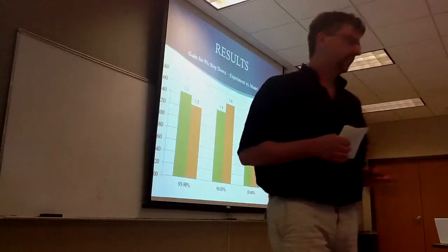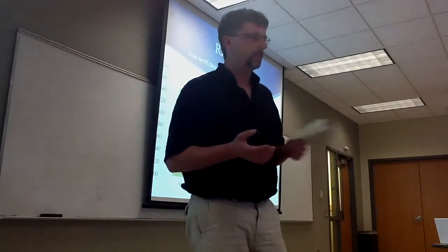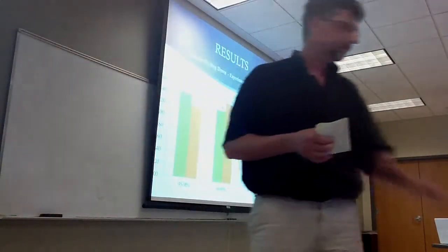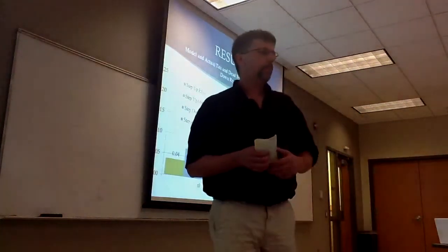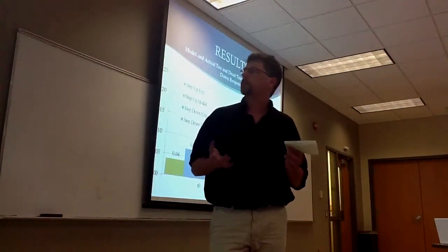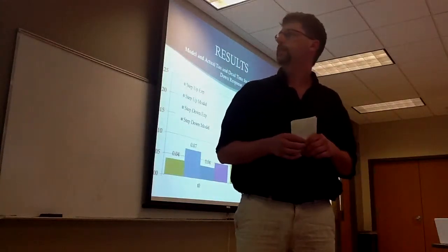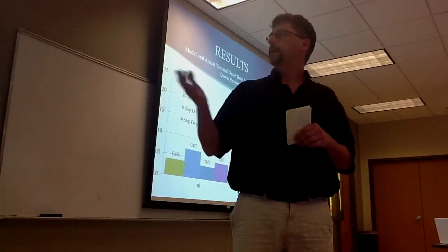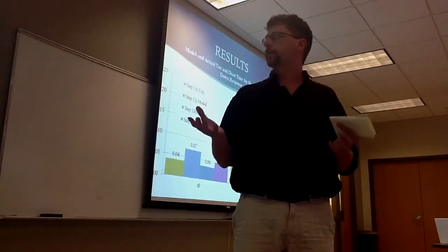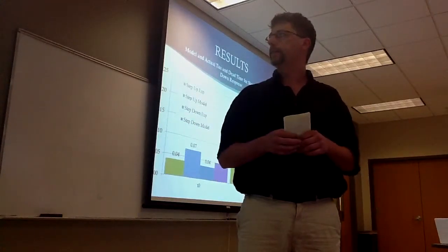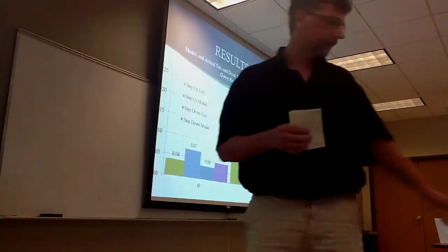Similarly, we did the same thing for the step down. There's 1.5 versus 1.3 for the step down for the actual versus the model, for example. The model versus the actual or experimental time constant, tau, dead time for the step up and the step down response here. The numbers are very similar between the model and the experimental data, as I mentioned earlier.